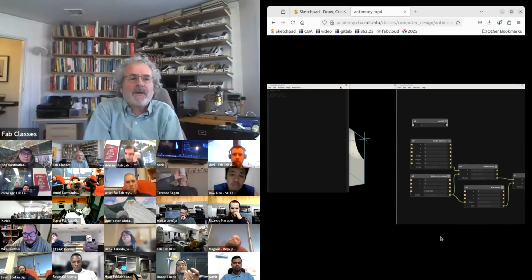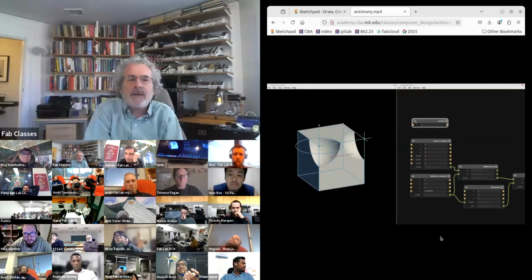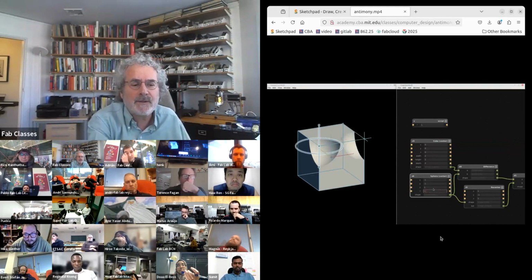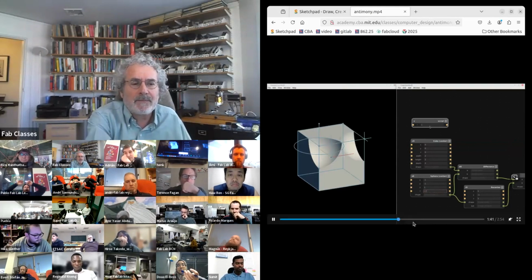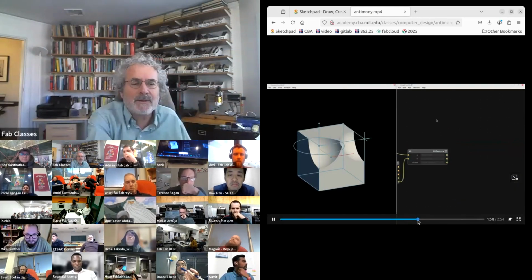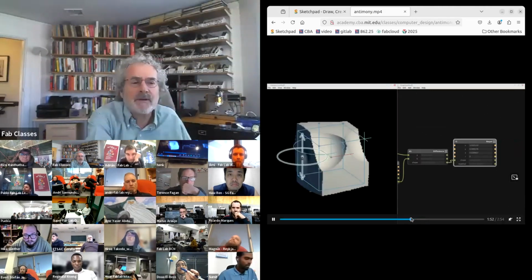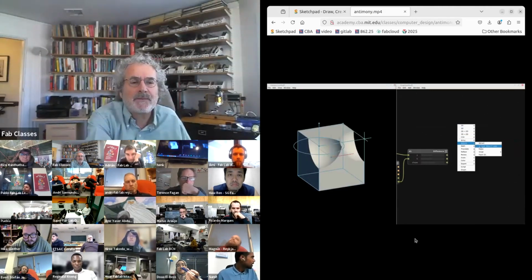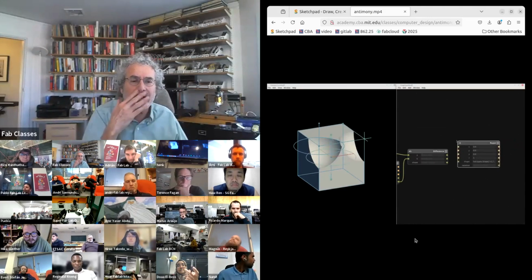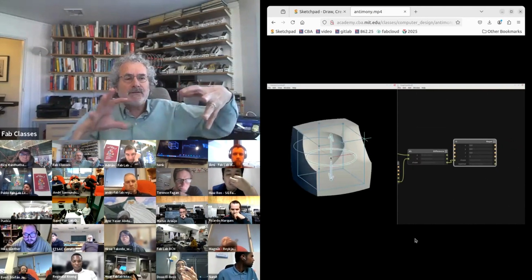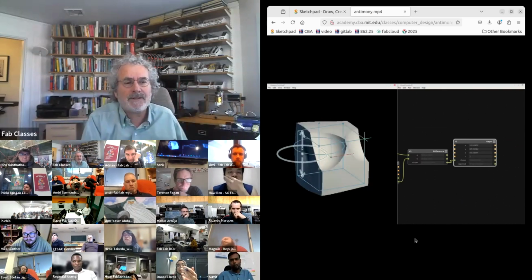So what I'm showing now is how you make it parametric. You can introduce variable nodes, and each node is a little program. So the variable nodes can use those. So far, that's still interesting, but now comes the fun stuff. Now I'm going to add a repulsion node, and this has no analog in other environments. This is going to completely smush the whole shape.